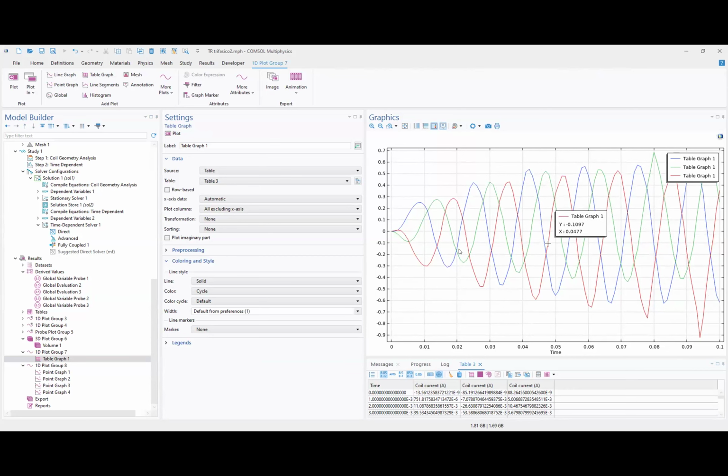But with this ramp step, we didn't see the inrush current. If we apply the voltage directly, the full wave, then we will see big current here at the beginning in some of the phases, depending on what time it is closing.